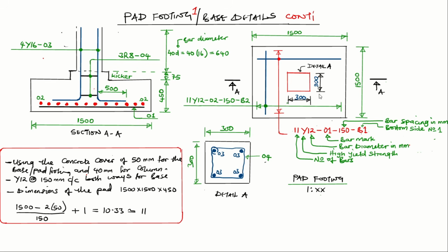Then after you draw your base, the next thing that you're going to talk about will be the section. This section that you had cut across. Now, in your section, the first notable thing that you're supposed to think about is the thickness of your base. So for example here, we have a span, and since we're cutting in this direction from left to right, we're cutting here, from here going straight to this space here. So now when we cut here, what we're going to remain with will be reinforcement. Now remember that this reinforcement, since we're cutting in this direction, we'll cut this one here. So as a result, on your section it's going to appear as dots, then this one will appear as a straight line, just the way it is.